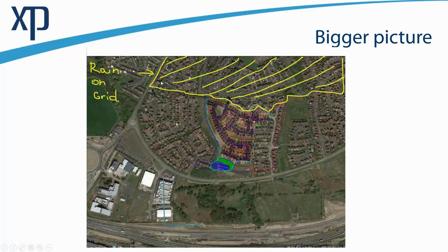As we don't know anything about existing drainage systems, assuming we don't, we will run it for a worst case scenario, considering that all the drainage systems located in the upper land are completely surcharged, and all the ground is 100% saturated. So there is no infiltration available, there is no space for water to go inside the drainage system. So all the runoff from this upper yellow area will just naturally come through blue-green corridors, right? It will follow the blue corridors and come wherever it comes. So let's see what will happen.